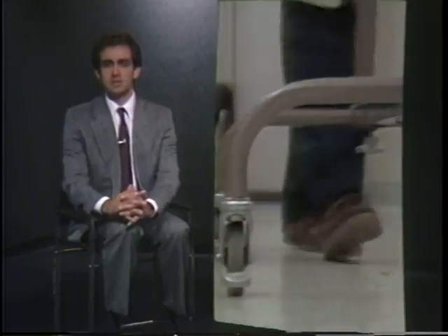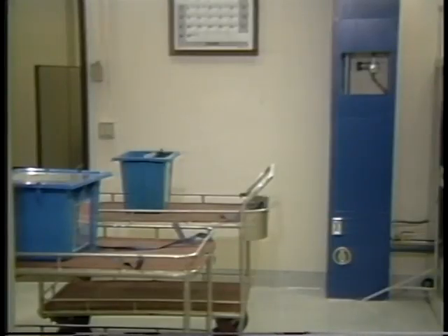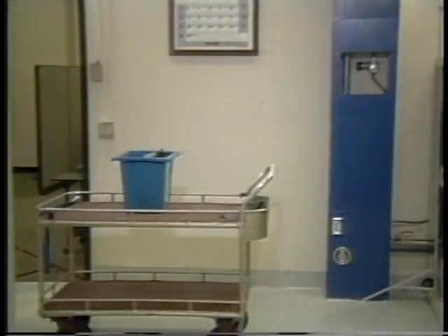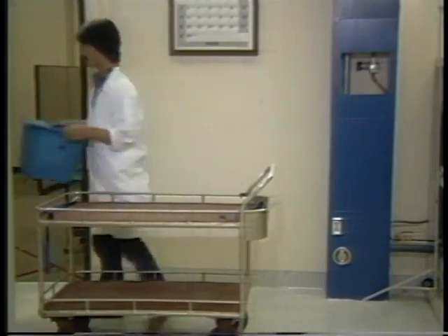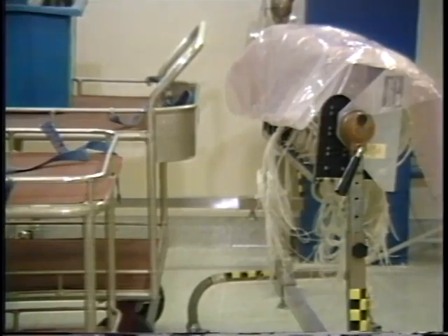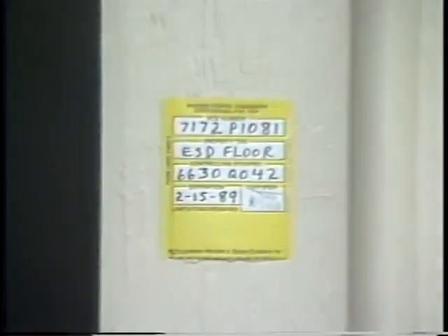For instance, if you are moving a piece of unprotected hardware, you must use specially certified carts. And of course, you must wear a leg strap. If hardware is protected with approved ESD packaging, it may be handled without ESD controls. Be sure the cart is certified by Process Control Engineering before you use it. Look for a valid certification label. If you are transporting unprotected ESD-sensitive hardware on a cart, the floor must also be certified as an ESD floor. If the floor is not ESD safe, the part would require protective packaging.